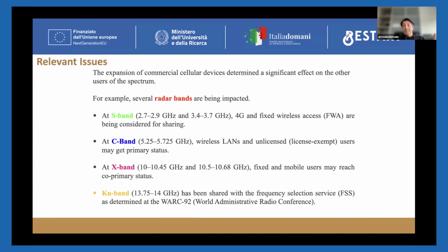And in these bandwidths, also other spectrum users exist. And these systems must therefore take measures to identify and also avoid such interference, or to employ cancellation techniques to reach a noise-limited condition, or I would say at least as close as possible, a noise-limited condition.